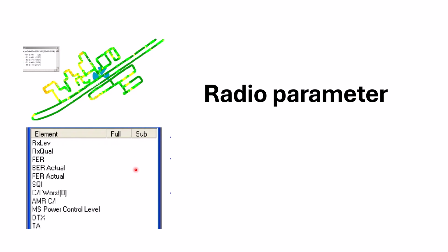Range is -10 to -65 dBm is very good. -65 to -75 dBm is good. -75 to -95 dBm is fair. -95 to -105 dBm is worst.